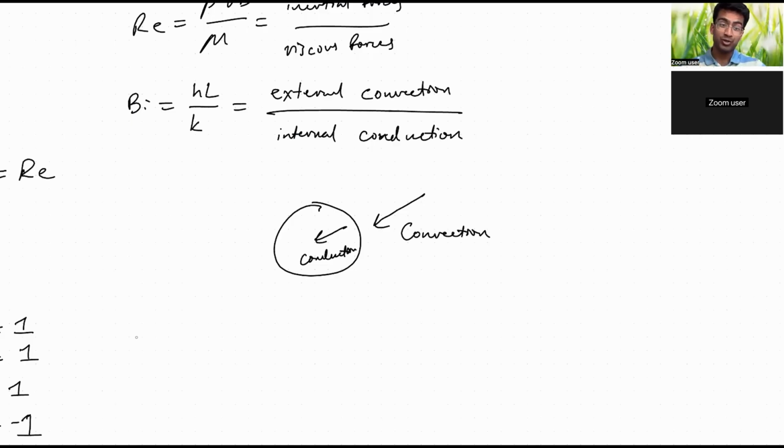Now, the opposite is true if you have a very high Bi number. In other words, conduction is really slow. Let's say you have a plastic ball or a really good insulator. Then convection is going to be much, much faster than conduction, in which case you have a temperature gradient across the ball, and then your heat transfer problem becomes a little bit more complicated and involved.